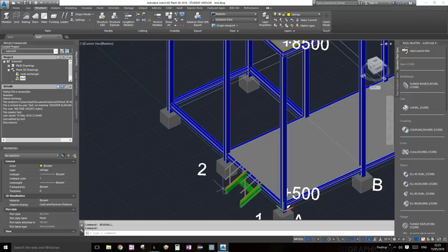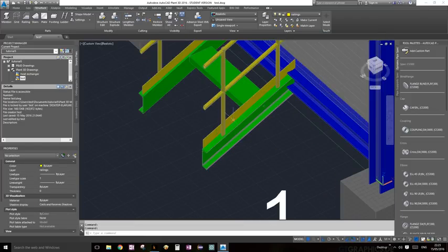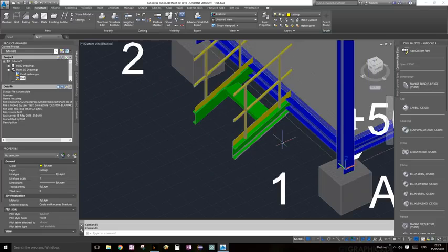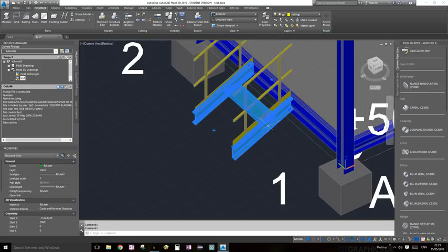Okay, so let's go ahead and trim our little C shape or J shape, however it's called here. First thing we're going to do is hide everything else except for our little channel. So we're going to select the stairs and go hide others.